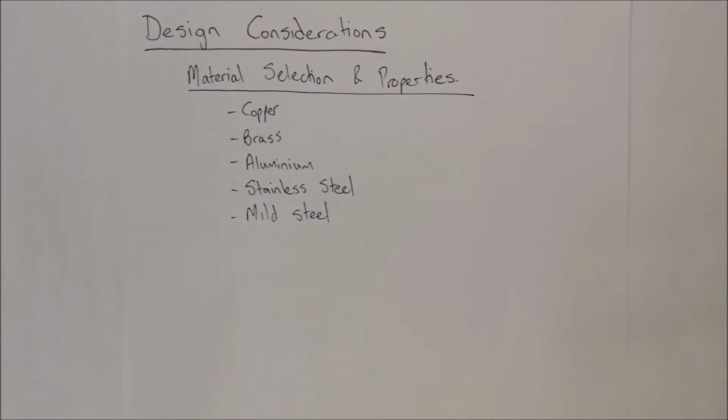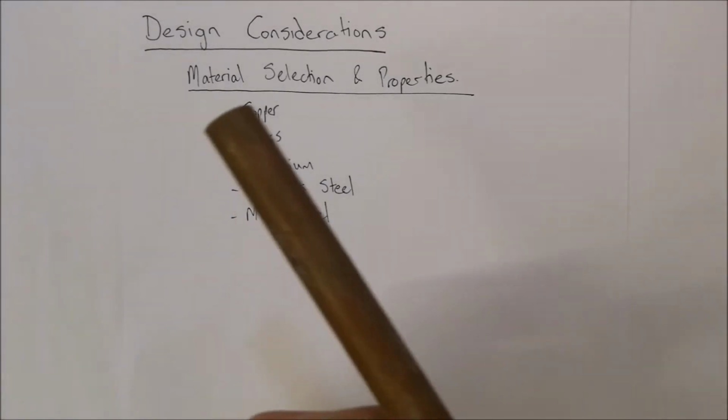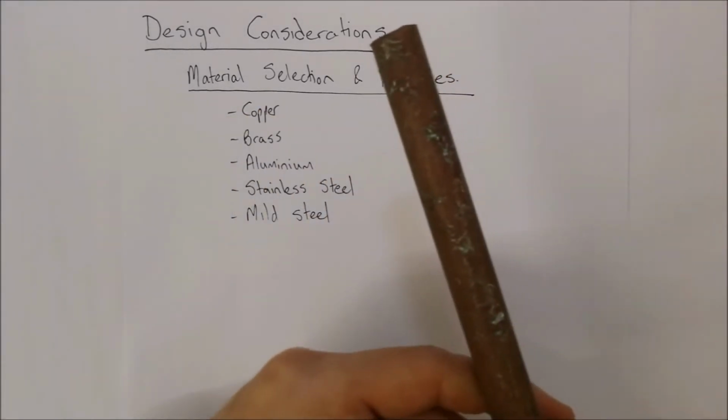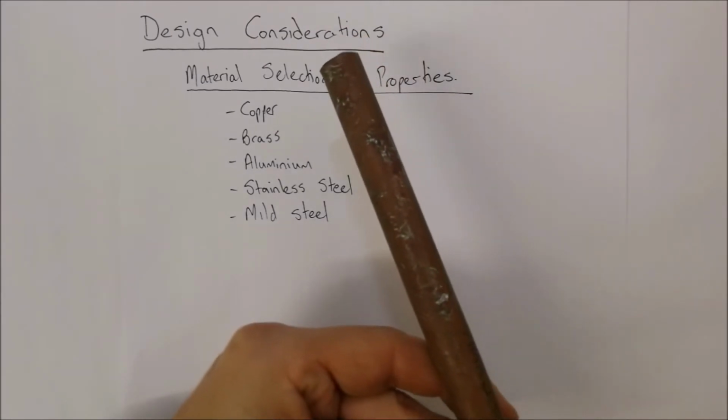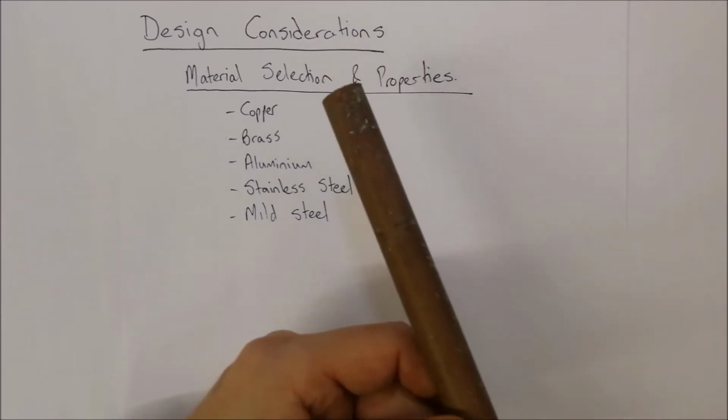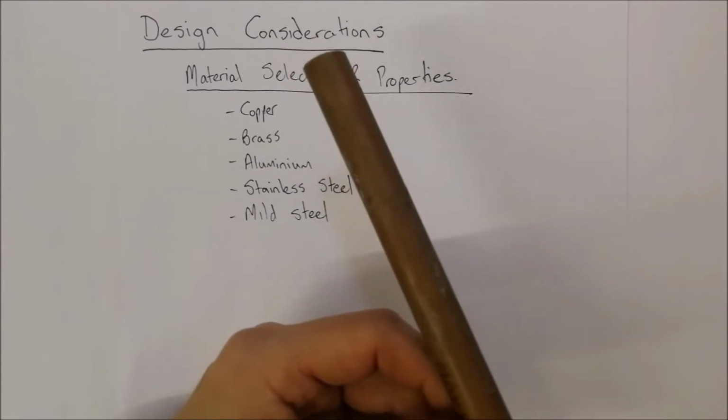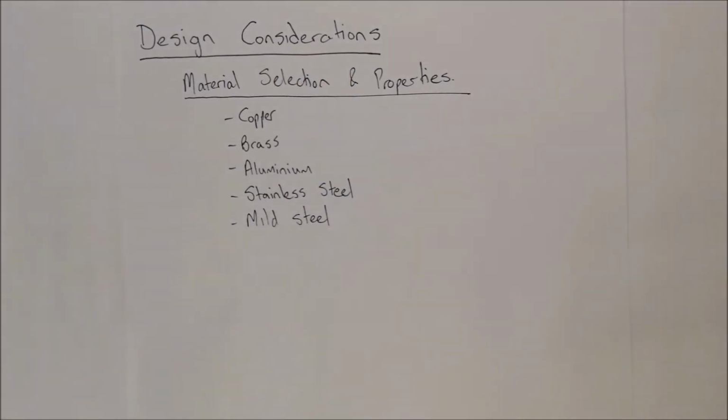As a matter of fact, I've got another pipe over here that has some corrosion on it, and you'll see it's almost a bluish color, and that is corrosion of the copper. Most of the time, if you look at copper sulfate crystals, which are also a bluish color, that is the type of appearance that you would see on these copper materials when they're corroding.